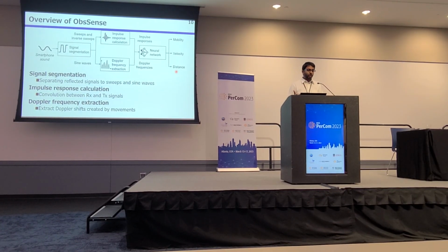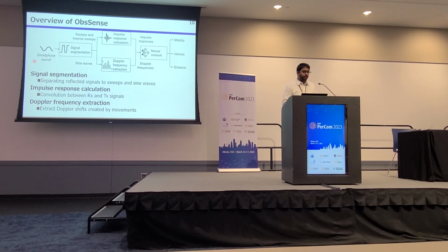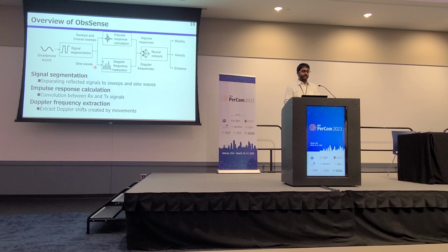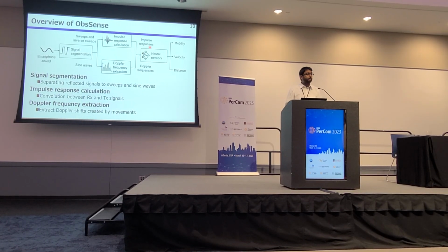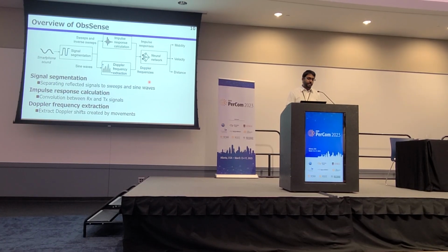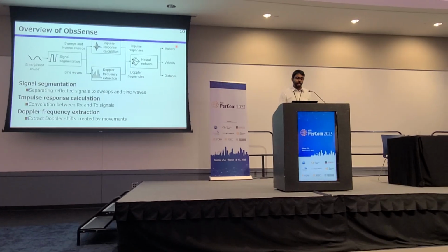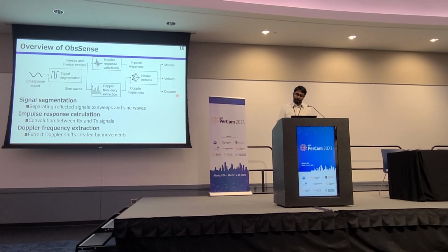So this is the overview of SenSE. First, we collect reflected acoustic data from the smartphone, and we segment this time series signal into sweeps and inverse sweeps as well as sine waves. And we use the sweeps and inverse sweeps to calculate impulse responses, and we use sine waves to calculate Doppler frequencies. And we feed them into a neural network which estimates the mobility, velocity, and the distance of the oncoming obstacles.